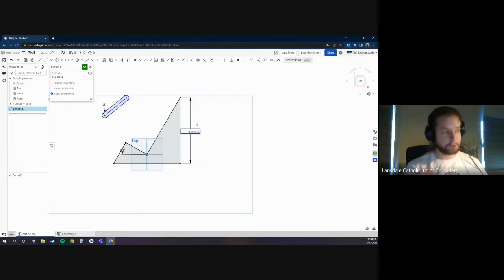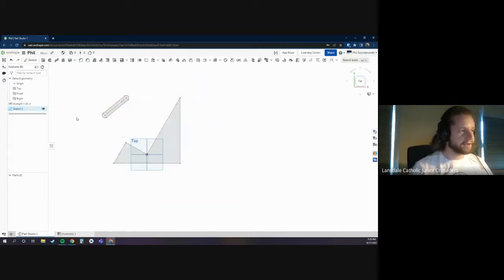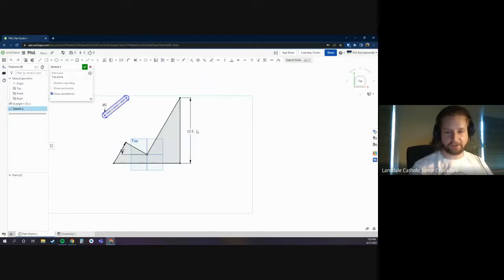And this is super useful if you're trying to change the size of something and you don't want to have to do that math over every single time. So this is like parametric math. It's kind of like an Excel sheet, but with CAD, where it'll automatically do the math for you the first time that you create it, and henceforward. Now, do keep in mind when you delete that dimension, its equation goes away too. So be careful with that.